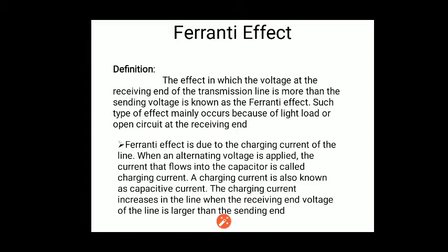We will discuss the definition of the Ferranti effect. The effect in which the voltage at the receiving end of the transmission line is more than the sending end voltage is known as the Ferranti effect. Such an effect mainly occurs because of the light load or the open circuit at the receiving end.